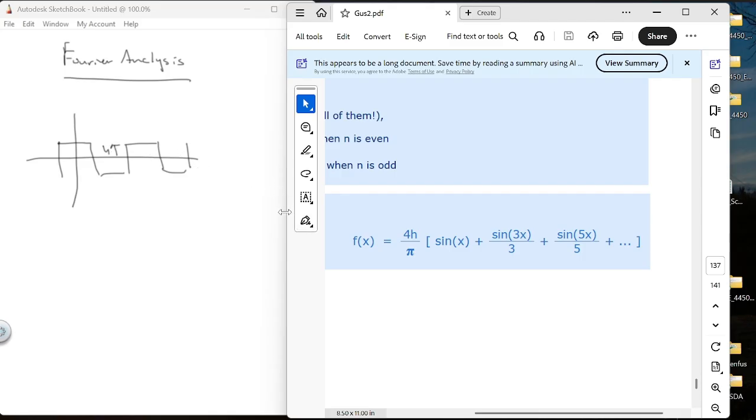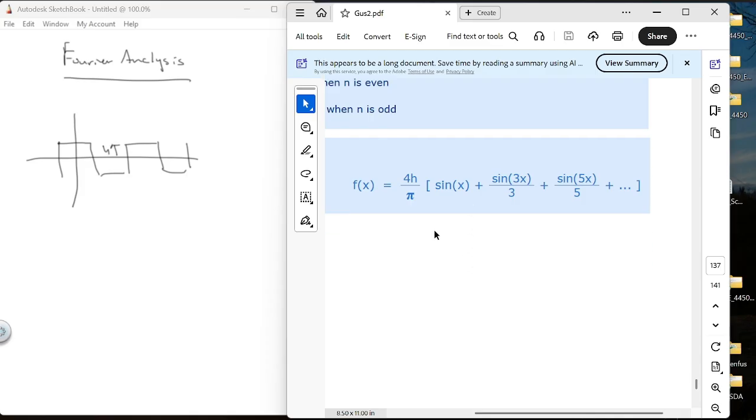That's why when you buy an inverter, it has filtering in it that does not allow the inverter to put these harmonics back onto the AC waveform that's feeding your inverter. You do not want this junk to escape back upstream into the rest of your circuitry. These are the things that you don't want.